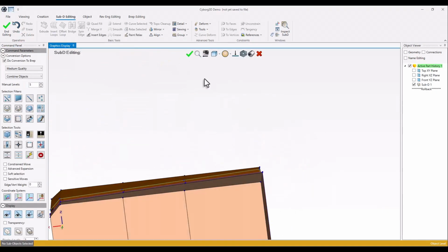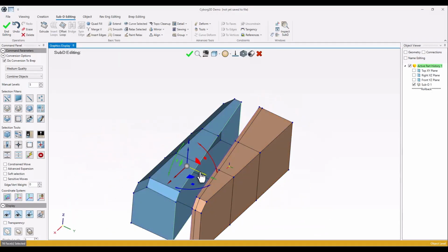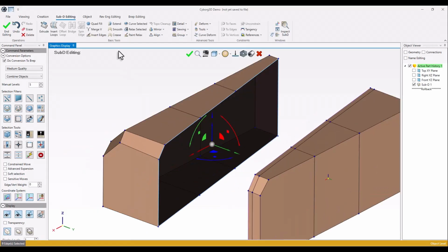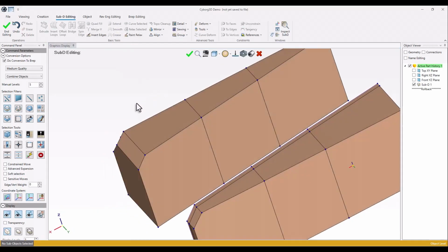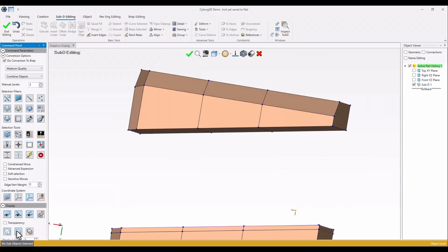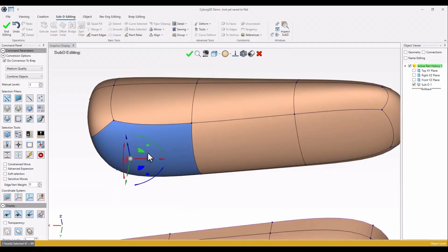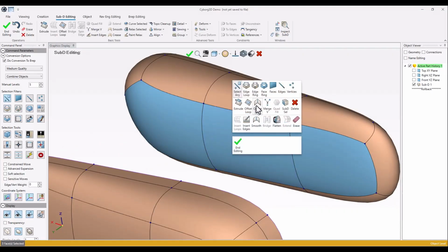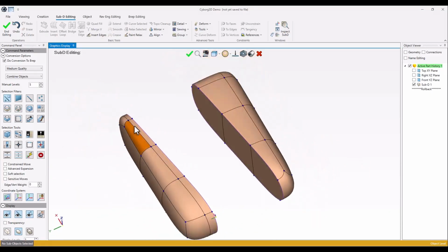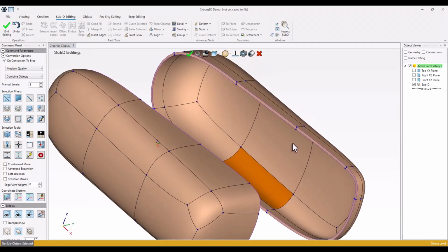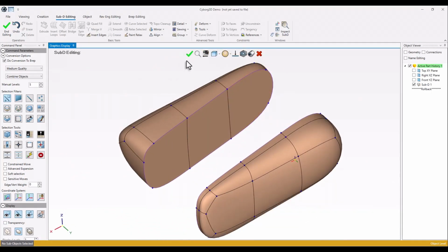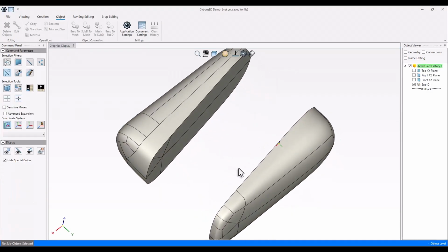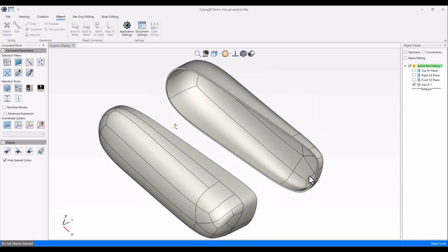Okay, so what if we need to close the other body? I can easily go to my edge loop, select this edge loop, and quad fill. Okay, so you can see with the subdivide mode, this is very smooth edges. I can select these three faces and right click, increase them to 100 like this. So you can see now we've got one thickness set and one is solid. Once I convert it, you're gonna see now I have one solid and one is shelled here.